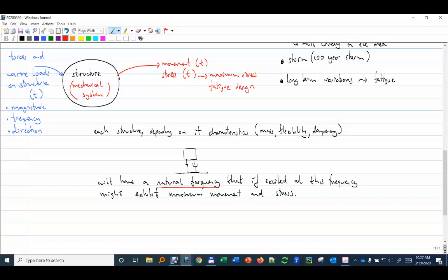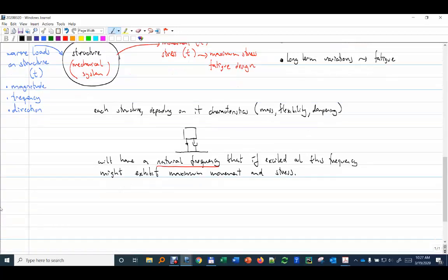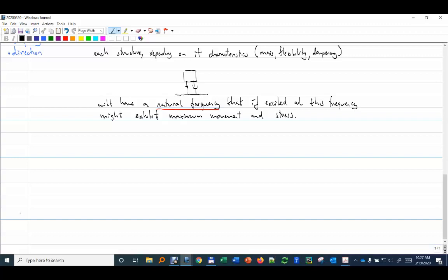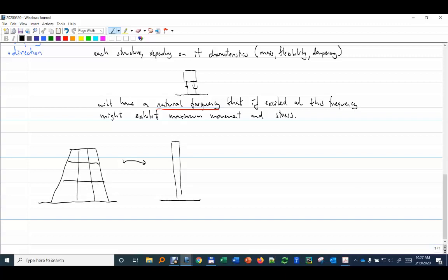So for offshore structures, for example, some structures have relatively limited movement. If we talk about a jacket, we can say an analog of that is maybe a bar which is drilled or fixed to the ground. So then you have some movement maybe in this direction due to the excitations you might have from the wind and the current, so you exhibit a movement just like a fixed bar. Okay, while if you have a floating structure,